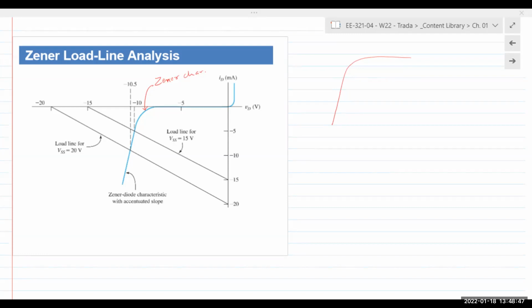So even a Zener diode that we say stays the same no matter what the input voltage is, there is always a slight variation, like maybe 100 millivolts, 10 millivolts. There's always some variation. So this is just an exaggeration. Oh, well, actually, it's written right here. So let's just use that.